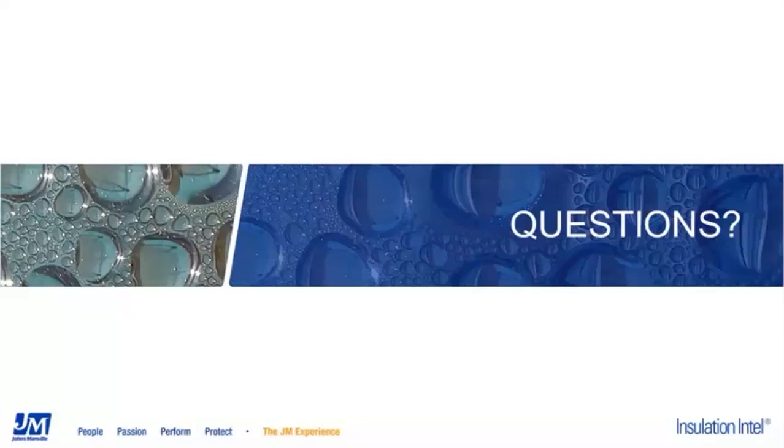Sure. So we did talk a little bit about elastomeric rubber earlier in the presentation, and the point that I think is most important to note with that type of material is that you need to put a vapor retarder on it if it's going to be used on a chilled water system. Again, the material itself doesn't have the appropriate perm rating, that 0.02 perm rating that you're looking for on a chilled water system. So you need to make sure that a vapor retarder is used if you're going to be using elastomeric rubber on a chilled water system.